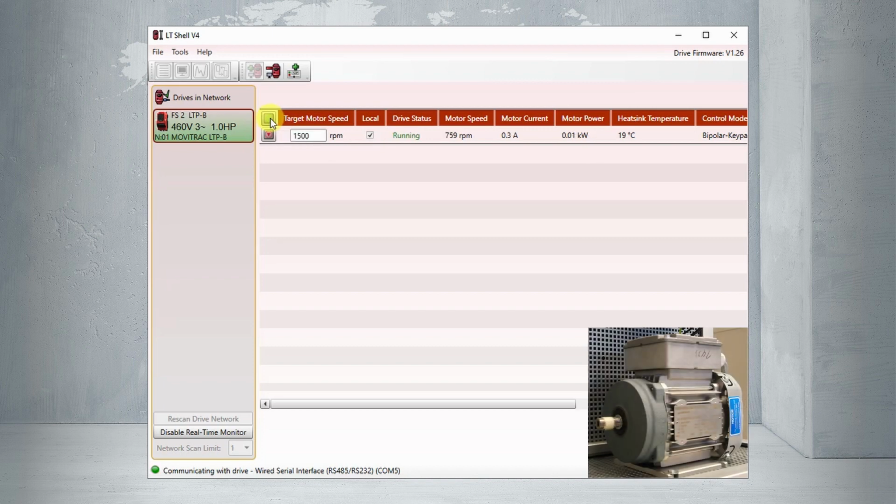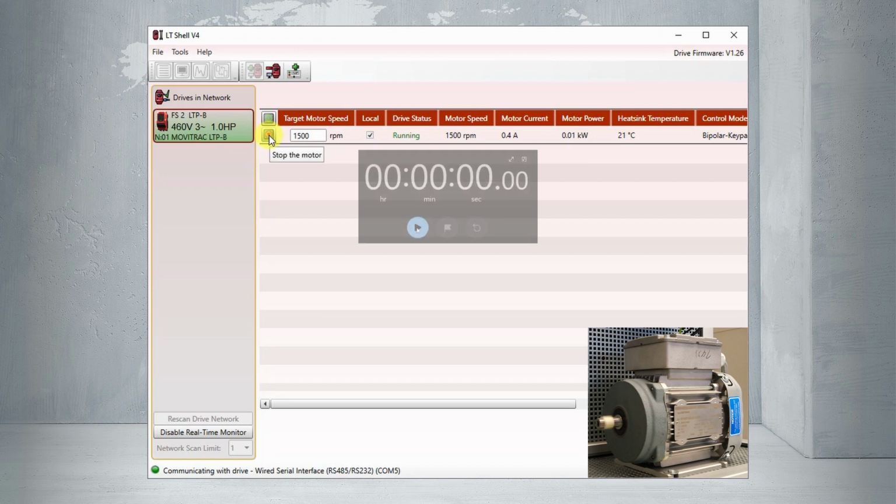And we've accelerated up to 1500 RPM. That happened very quickly because we had a 2-second ramp. Now we're going to time the deceleration. We're going to come down from 1500 RPM to 0. That should take 10 seconds, so let's go ahead and time that. And it definitely is taking some time to decelerate, so I think our ramp is working, but we'll let the stopwatch confirm it. Okay, I think that definitely confirmed it. We had a nice 10-second deceleration.